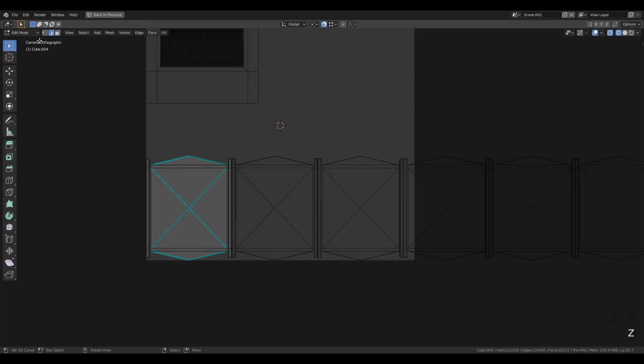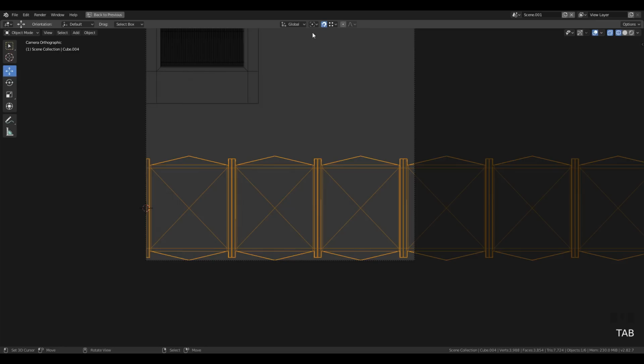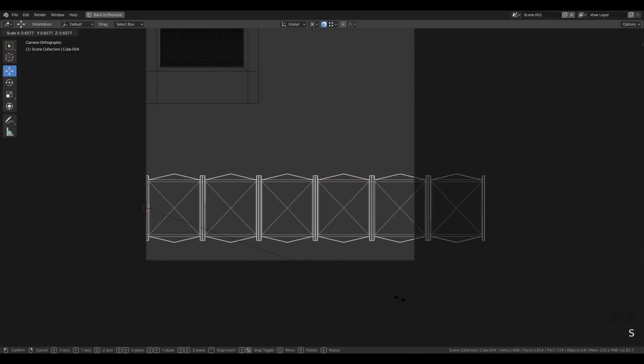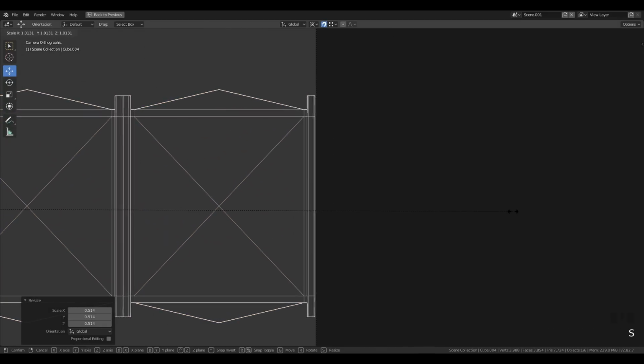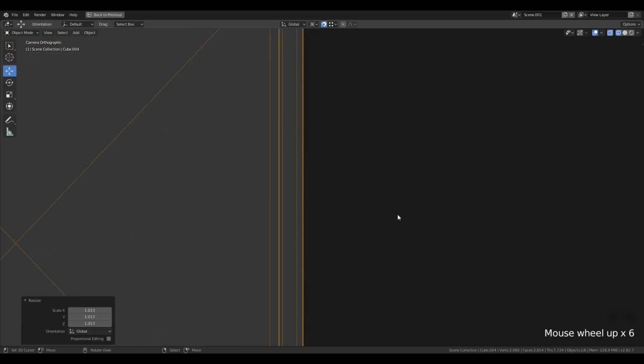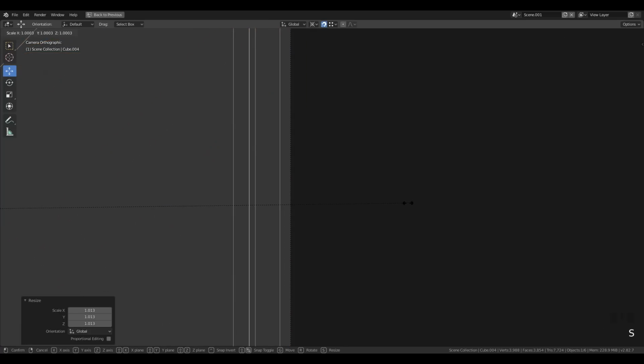Then in edit mode, select the top edge of the mesh and apply 3D cursor to the selection. And then change the pivot point to 3D cursor. Then you can scale it down easily so that you can focus only on other end of it. Try to match it with the plane below. That's how I also create trim sheets. It's easier and effective.